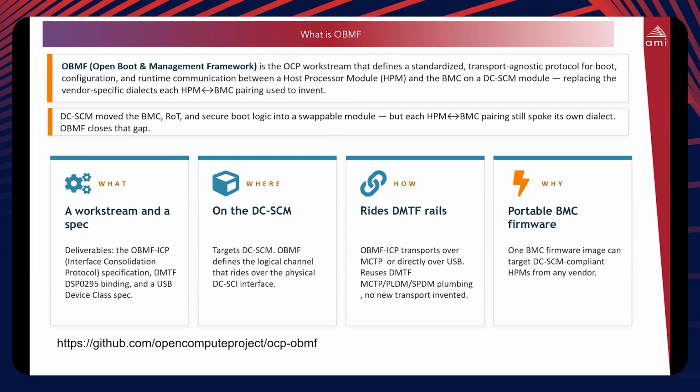So my next topic is another one that we see a lot more discussion on today, called OBMF. OBMF is Open Boot Management Framework, which is transport agnostic. The big reason is that, looking at BMC development, we tried to decouple the hardware and software, and that never worked. We did the DC-SCM, which still didn't work because you still need to have this SCM and HPM pairing, right? So OBMF is actually trying to close this gap.